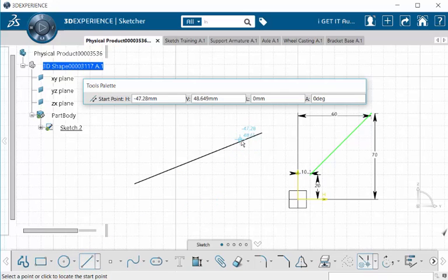When selecting the line again, you can see here if I drag my cursor across it, and I can find the endpoint, a solid blue dot and a concentric circle around it is shown. Go ahead and click and then drag. I also can make this line perpendicular to the one I just created by simply moving it slowly until a perpendicular symbol appears.